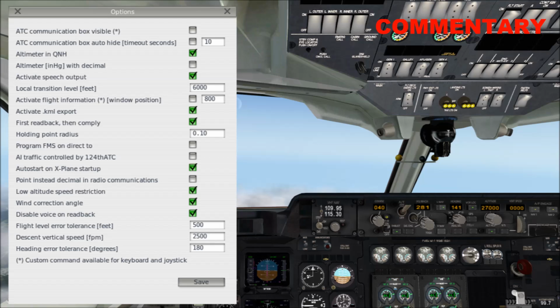If you prefer to do the talking with ADC yourself, you should select the Disable Voice on Readback option, and you can only hear the ADC talking and not your own requests or readbacks. The flight level error tolerance tells the plugin at which altitude deviation to inform you, like you're 600 feet below your assigned altitude. In order to calculate the top of descent and provide the first descent instruction, you need to set the typical descent rate of the aircraft you are currently flying.